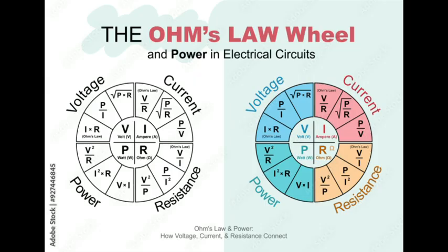So I bring the power directly to the switch, and then from the switch, I'm also going to make a splice where I'm going to be sending power to the next light, right? And through this splice, I'm going to make the splice right here. Through this splice, I'm gonna be sending power to this light, and through this splice, I'm gonna be sending power to the next light. So this allows 120 volts to come to the first light, 120 volts to come to the second light, and 120 volts to come to the third light.